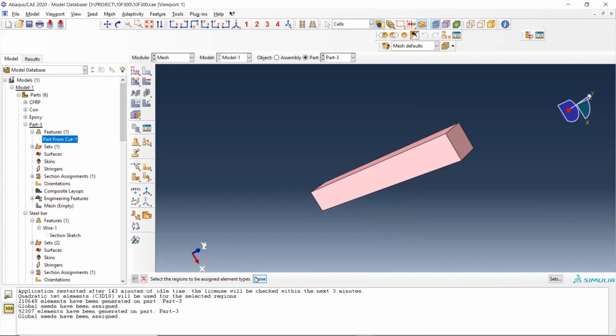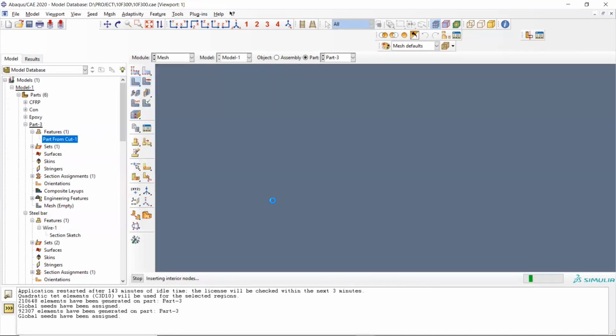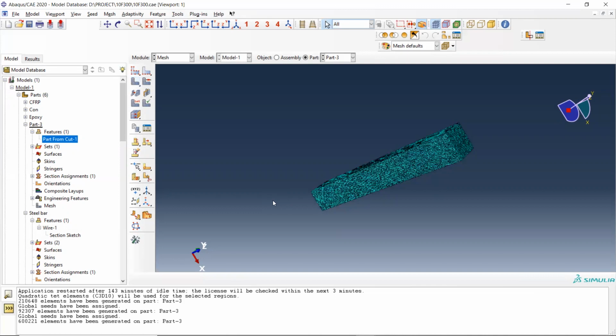So for attaching the reinforcement to the concrete, the constraint which I used was embedded, and for tying those stirrups and bars I used tie constraint. But those are just tied up, right? So you are using tie constraints. Tie constraints need not have the same node numbers and all. It can be any node numbers. No, I was asking about the embedded one.